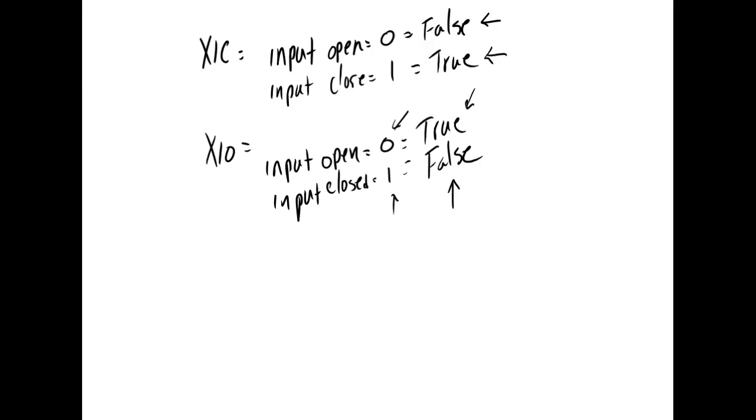Now ours don't do that, but ours has a switch on. These disconnects right here have a switch on. So these e-stops don't latch down, but to get it back, you have to get a key in. You can pull it out, but you have to get a key and put it in. I don't know if that e-stop is like that now or not. On our motor controls, you don't have to turn it and pull out the e-stop, but you have to have a key to enable it.